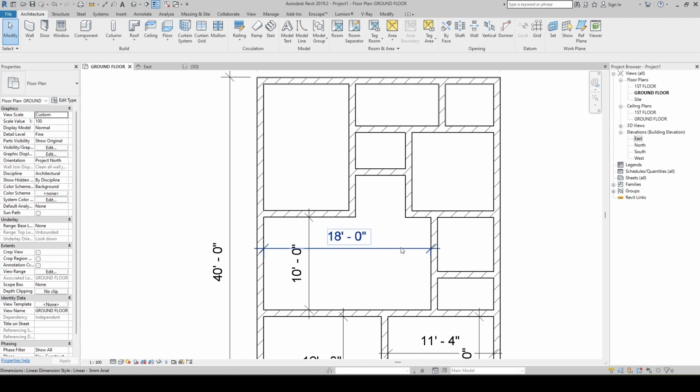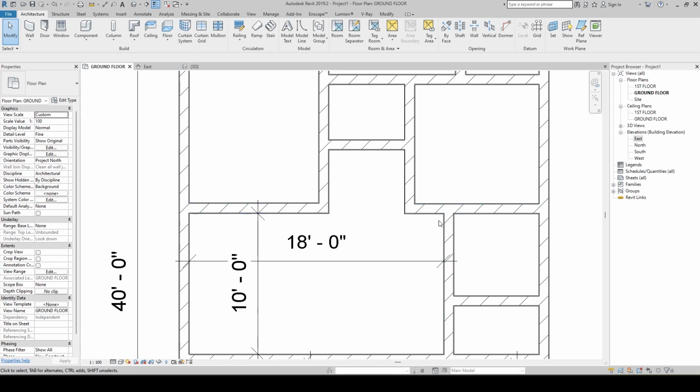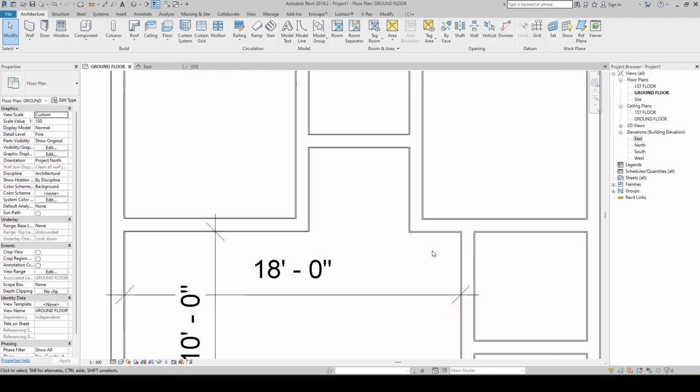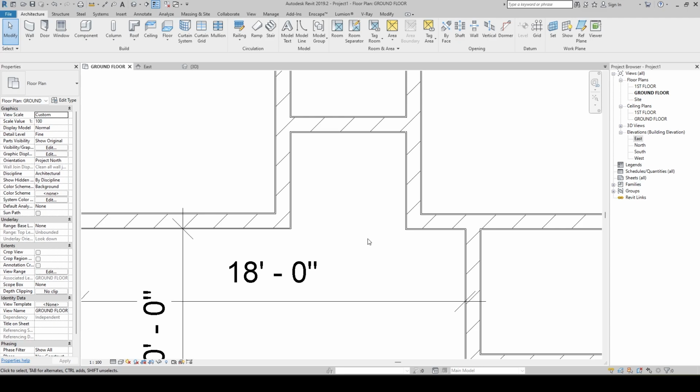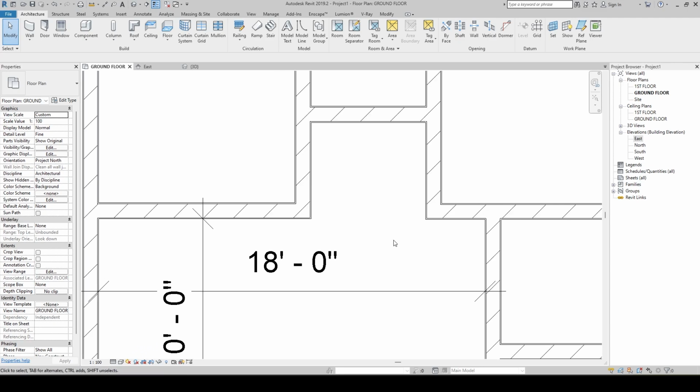As of now these two walls are not in line. In order to make them line up, you just use the align command, AL. You select the level where you want to keep the second wall, then you select the primary wall, and make the alignment.